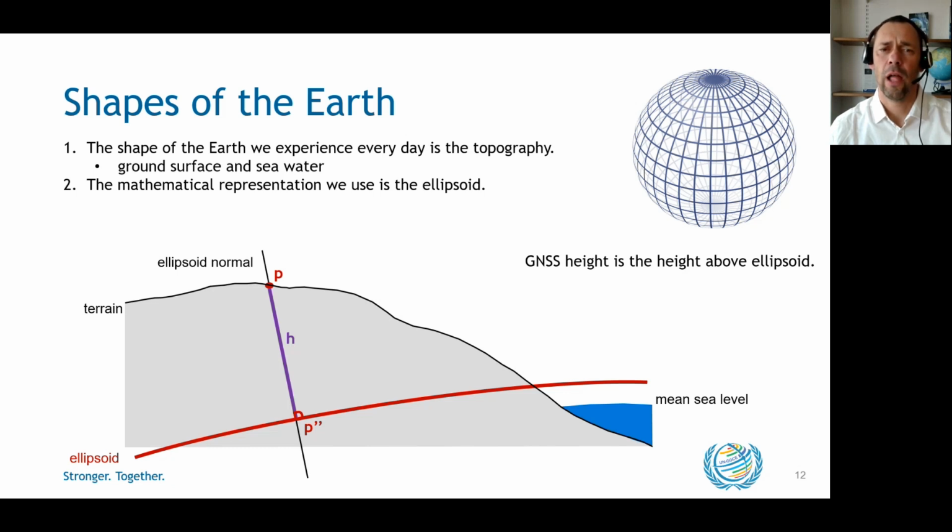The ellipsoid is the geometric zero surface we measure the height from. Additionally, in purple, we display the ellipsoid normal, which is the straight line along which we measure the geometric height. Therefore, the geometric height of the point P on the Earth's surface is the height described with small h.